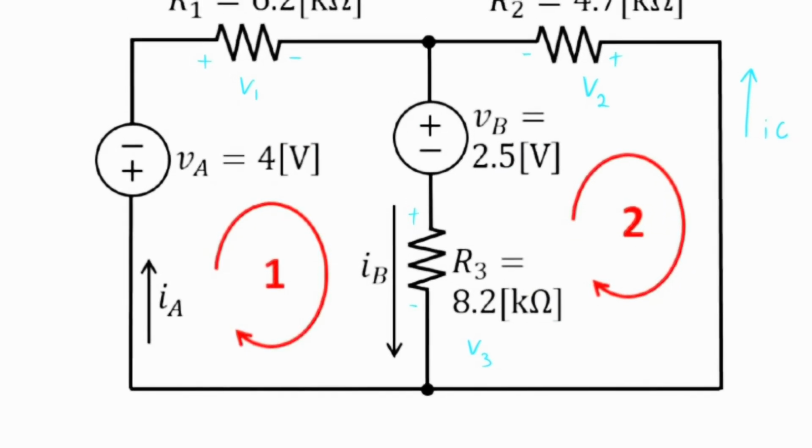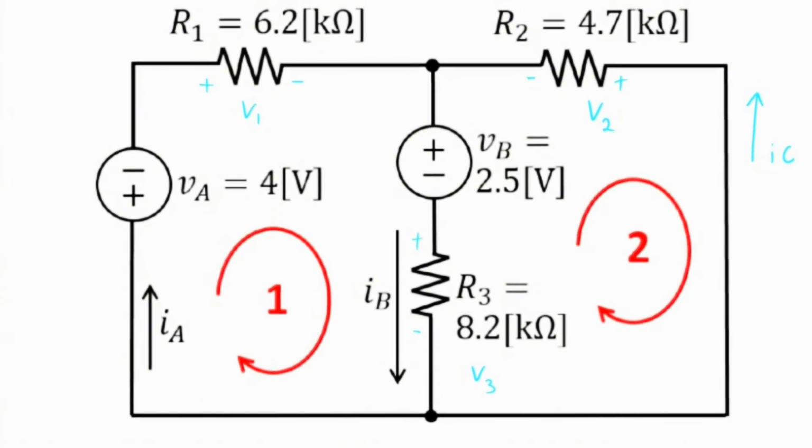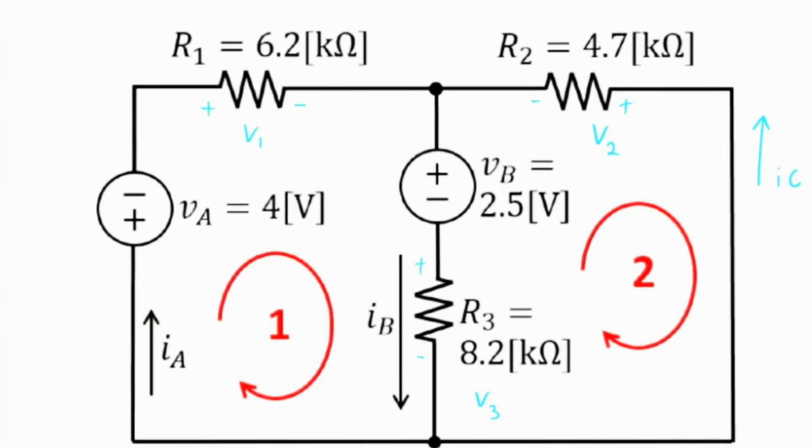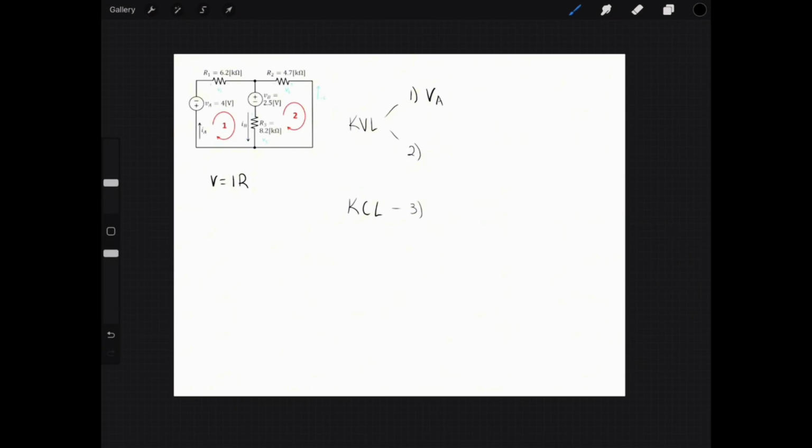Here is a diagram of the electrical current with defined values aligning with Ohm's law, which is V equals IR. In order to solve this problem, we're going to need three equations, one for each of the variables. For the first equation, we're going to write our equation in the direction of the red loop. This is for the left side of the circuit. These values are going to be positive because they're going on the positive end of the battery and charge first, indicating that they're flowing with the current.